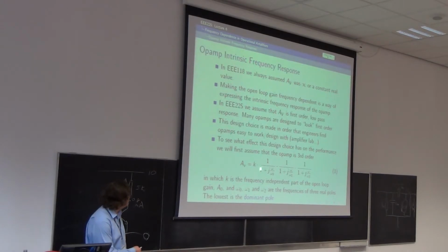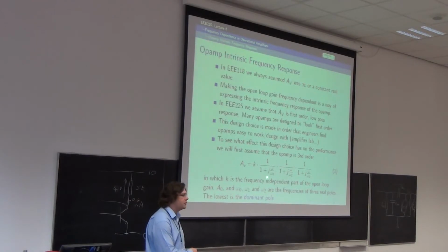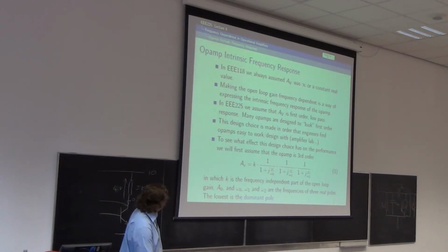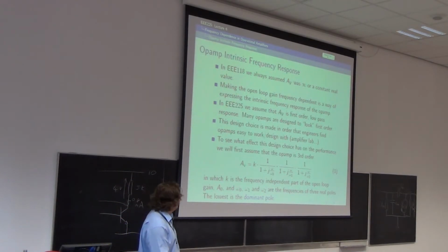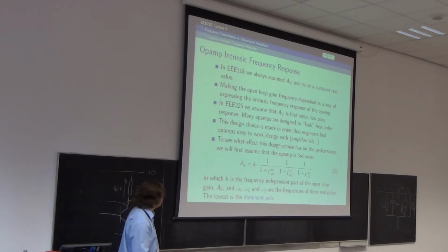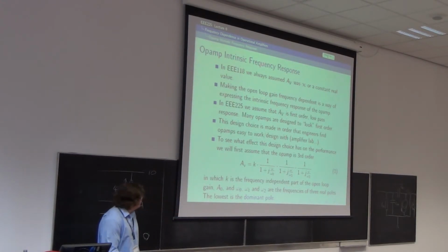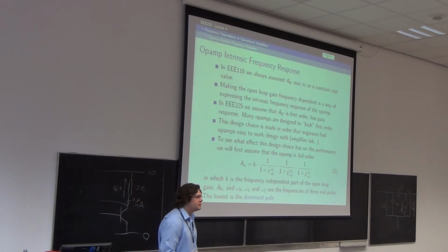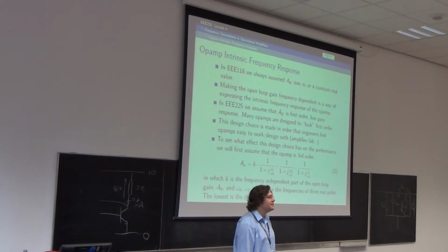So we have a first order equation here, which is K times 1 over 1 plus S tau if you prefer. But I don't want to just say, oh, it's first order, let's all not worry about it. I want to make sure you're clear as to how it becomes first order. So I'm actually going to make it third order, and then we're going to work backwards. So we have 3 real poles. Is this system capable of resonance? Now we'll see who's really paying attention. Oh, you only just started second order systems, haven't you? Then you won't know the answer to that.